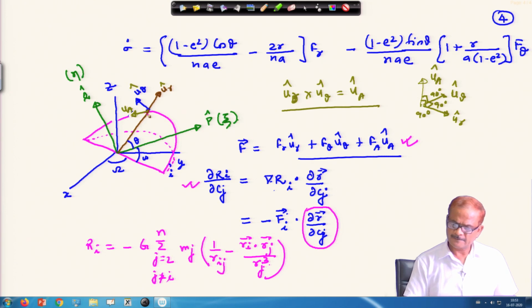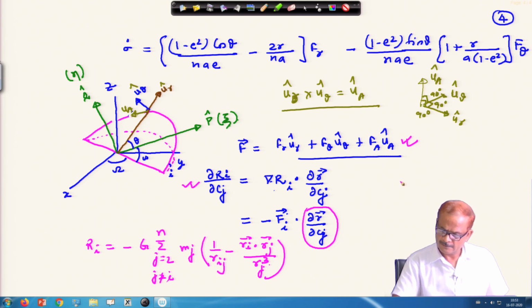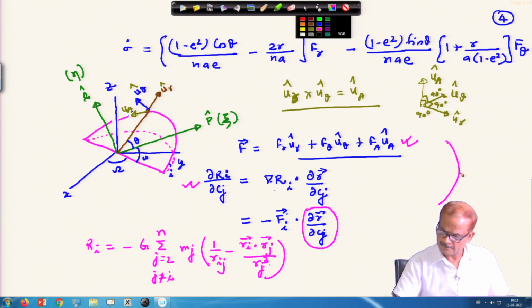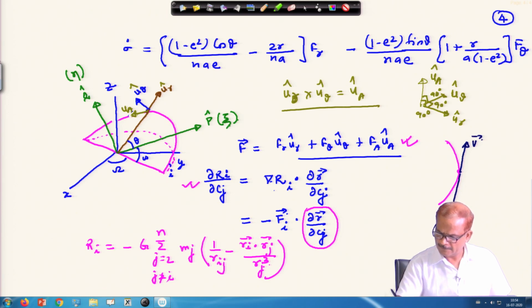So, different models are required in different places. Say if we are looking for aerodynamic drag. So, aerodynamic drag always by convention, say if this is the orbit, and then at any point the velocity will be tangent to this. So, velocity tangent we can show it like this. So, this is the velocity direction, and therefore, drag will be opposite to this. This is by convention. And therefore, we need to find out the force along the tangent direction, while here this is not along the tangent direction.